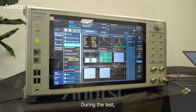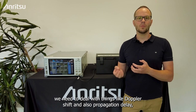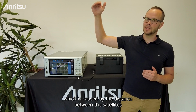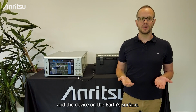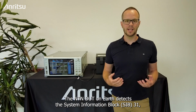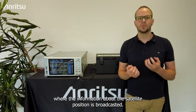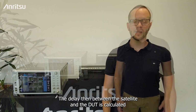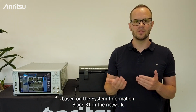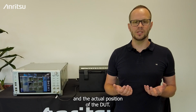During the tests, we need to deal with things like Doppler shift and also propagation delay, which is caused by the distance between the satellites and the device on the Earth's surface. The NTN DUT on Earth detects the System Information Block 31, where the information about the satellite position is broadcasted. The delay between the satellite and the DUT is then calculated based on the System Information Block 31 in the network and the actual position of the DUT.